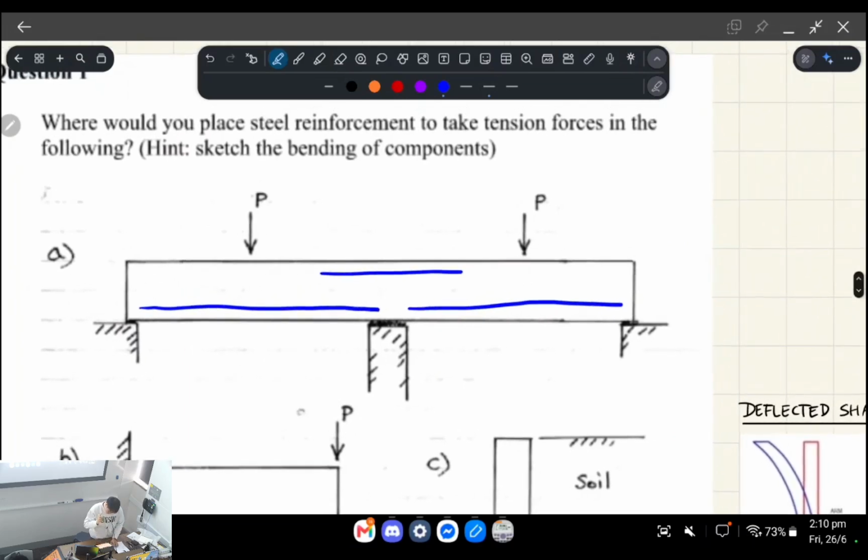The one thing you guys missed is what I was saying with the anchorage. It is better to have these cogs at the ends for tensile anchorage, because it gives you a faster development length and it ensures that your beam will behave essentially like one beam, instead of two separate materials.